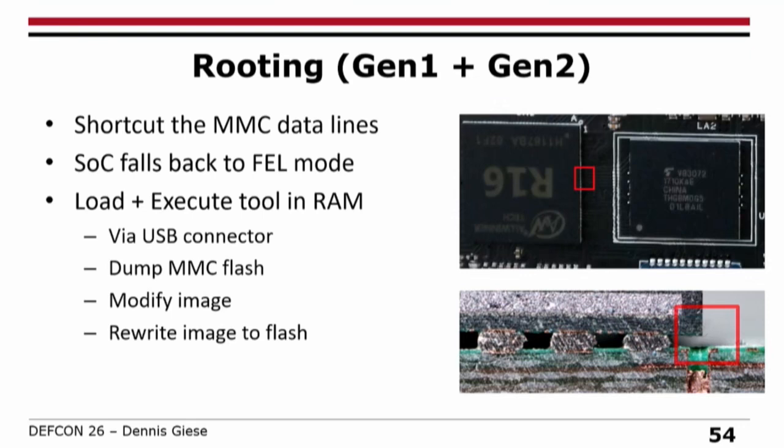As soon as the device was trying to boot up the image from the MMC flash, it wasn't possible, so it was falling back into the FEL mode, and then we could access it over USB, upload a small tool which dumps the whole MMC, modify the image, and rewrite the image again to the flash. So this was our initial way how we got access to this device.